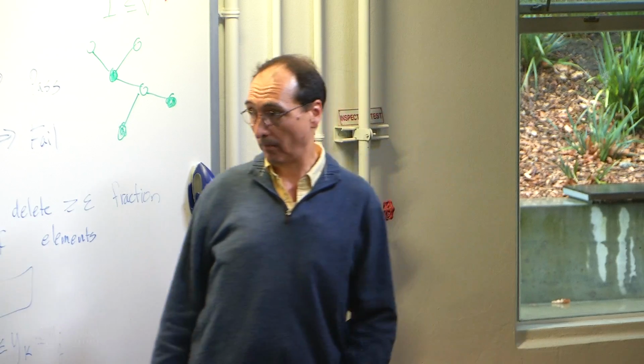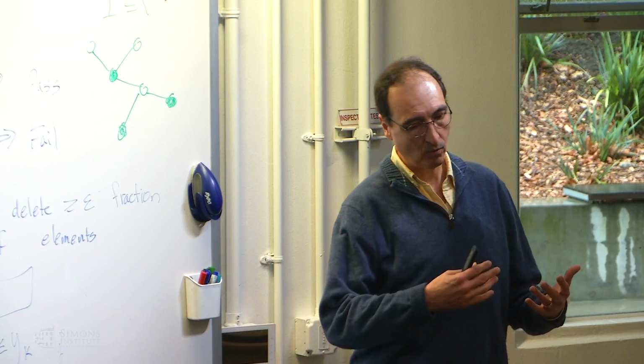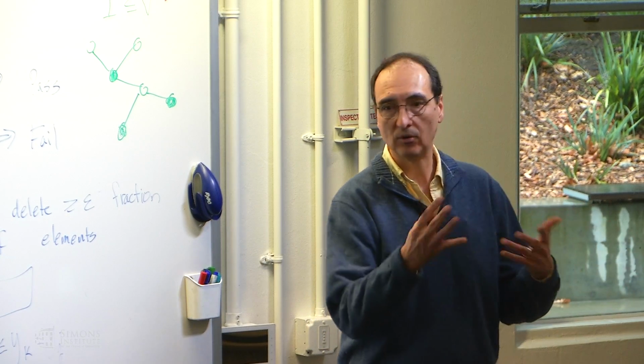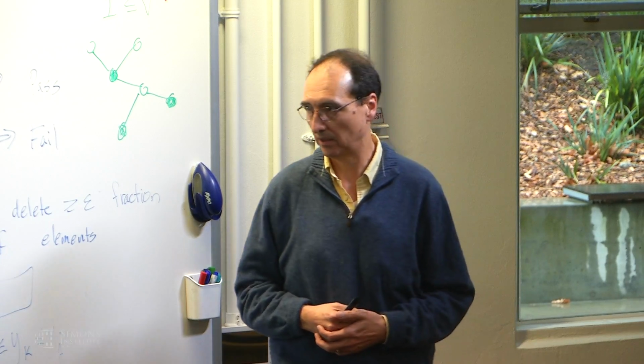I want performance, so I, for example, want to track the reference. And again, I would say something like I want, within 5 seconds, to be within 10% of the desired value, and within 20 seconds to be within 0.1% or something like that.